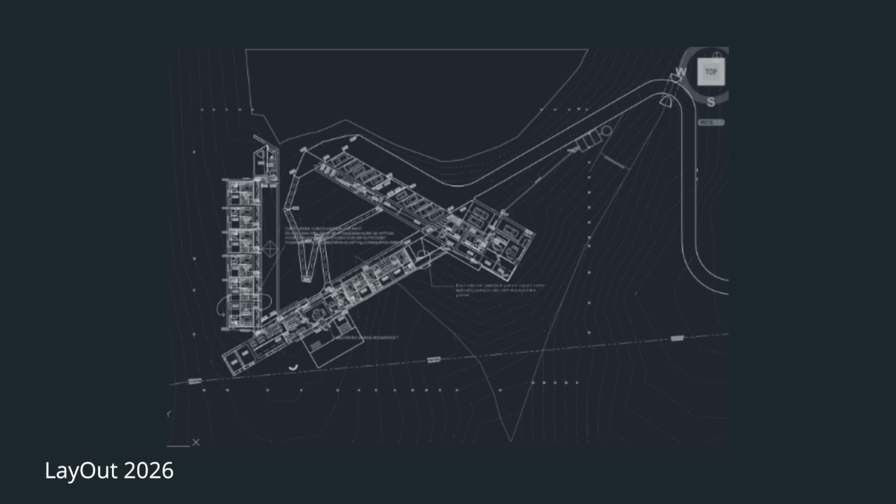If you have a LayOut workflow where you stack SketchUp viewports on top of each other, in the past, before 2026, if you exported those to DWG, you know that they kind of don't stack in the export. But now with SketchUp 2026, with stacked SketchUp viewports in LayOut, you export that, and then the DWG will show what you'd expect, all the viewports stacked on top of each other.